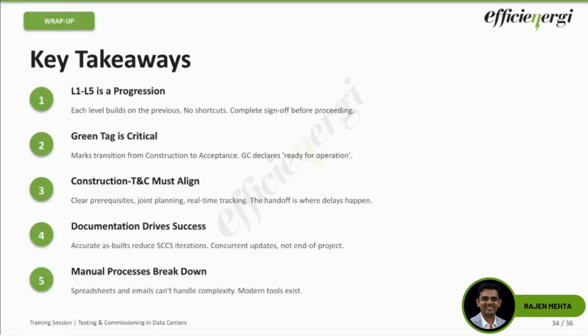So ideally you want to apply AC signals while you are testing the insulation healthiness. That's the reason you do that. And a higher DC voltage, if you apply during a hypot, can become destructive for the bus duct. So that's one of the reasons that you do not want to apply a very high DC hypot voltage.